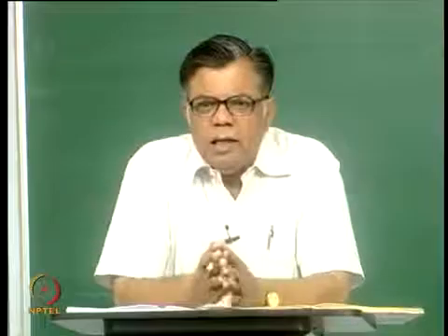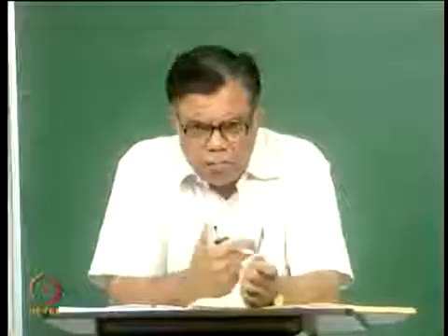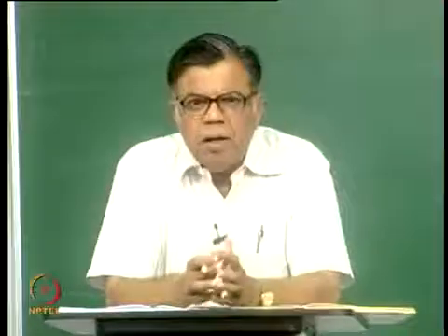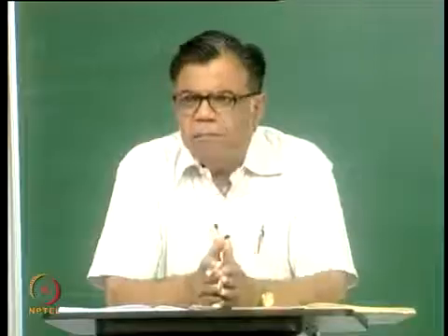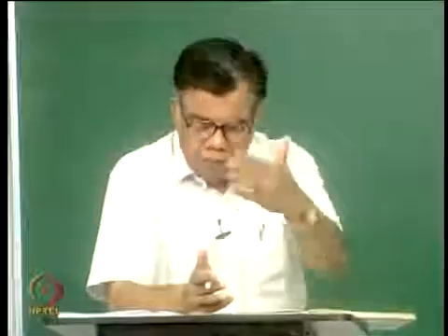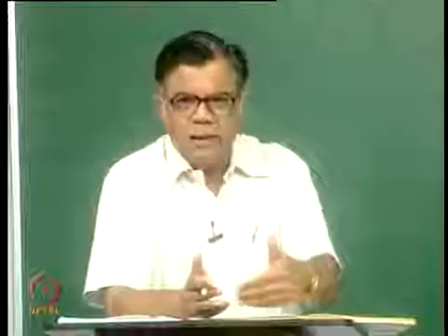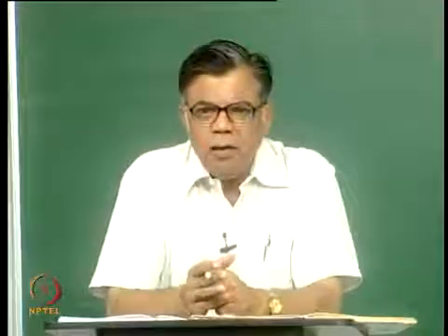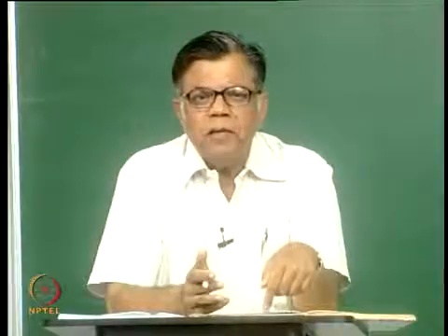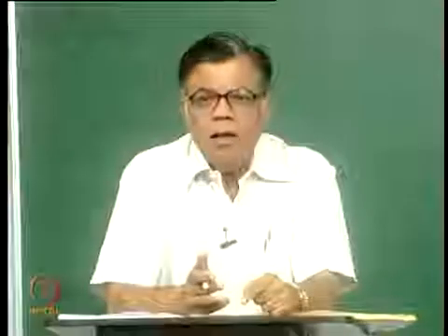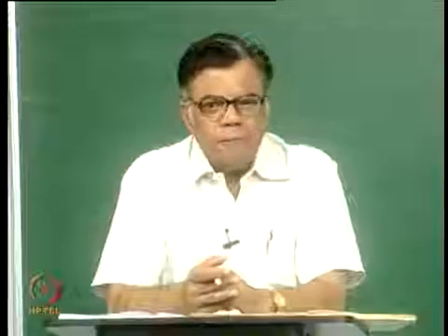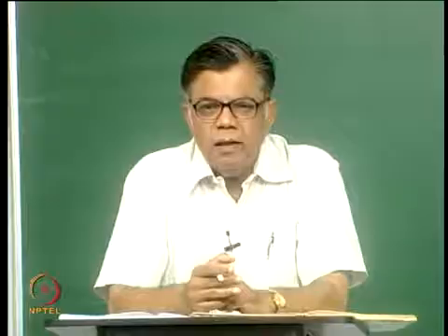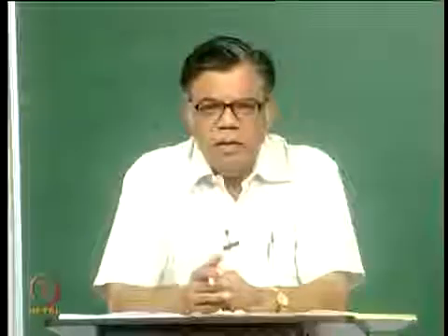I will give you a hint. You will get a very well known non-dimensional number out of this by slight manipulation. You are jumping, fine, fine, we will get the Eckert, but a more familiar non-dimensional number, you have a mu, you have a k. How to get a Prandtl number there? Multiply, divide by Cp, and now you see what you are getting. Only now you get the Eckert number.